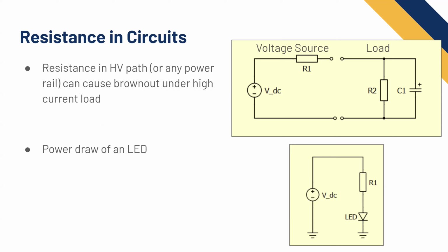Anybody have any ideas for the power stuff? So equation, yeah. Yes. So one thing we could do is power is equal to V squared over R. That is good if you have a voltage across the resistor, you have voltage and resistance, and that'll tell you how much power this is dissipating. But if you just did the 4 volts here, that would tell us how much power this component's dissipating. In this case, we want to know the whole system.